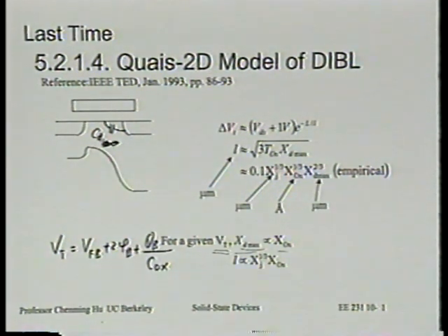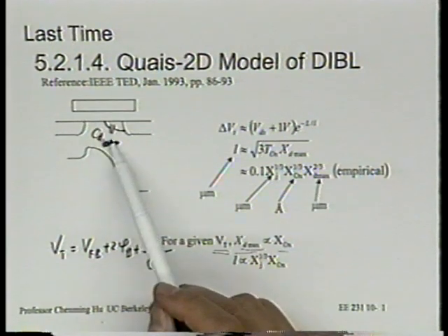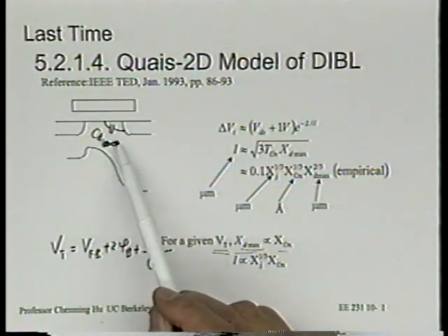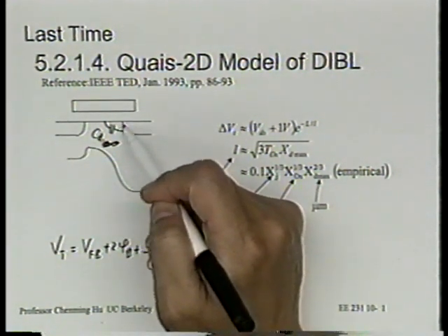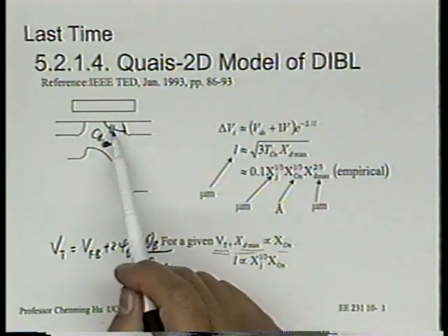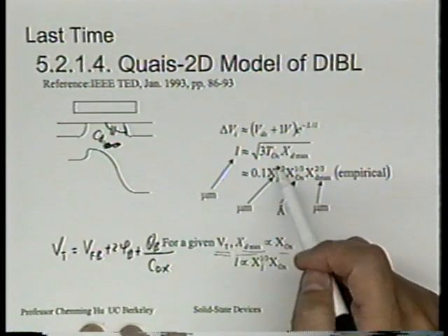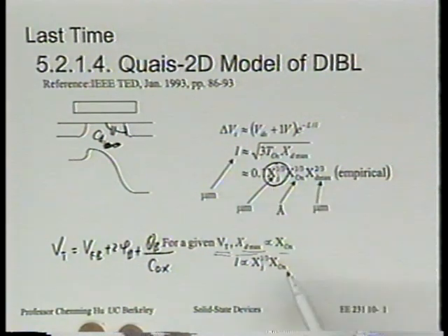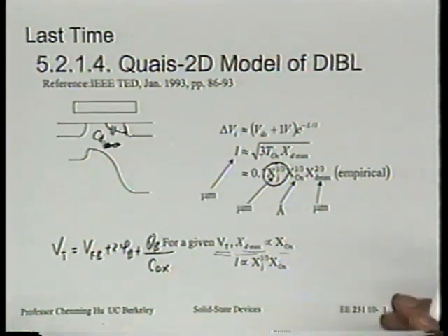Another thing that's not so intuitive, and perhaps at first look will give you this impression, is to say CD is linearly proportional to the junction depth, because you would visualize the junction depth as the size of that capacitor plate. You follow what I'm trying to say? You might get that impression. Now, this concept is totally not supported, whether you use simulation or any other solution of a 2D Laplace equation problem, such as separation of variables. You would not find that this capacitance is linearly proportional to xj. And indeed, you can interpret this as being the CD term, kind of related to CD, put this way.